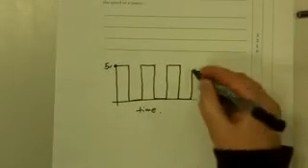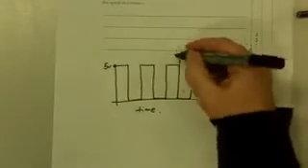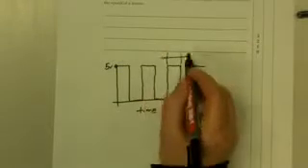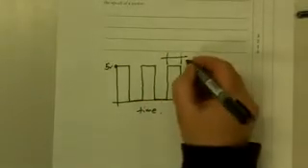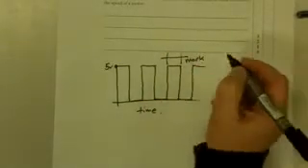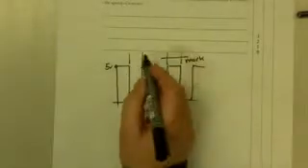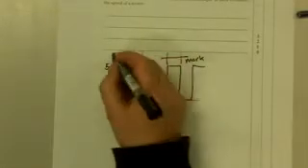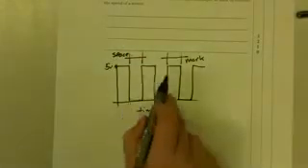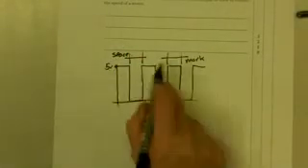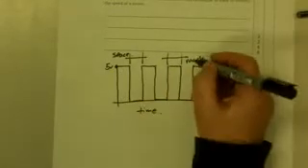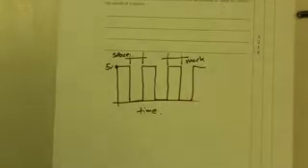And you need to label that pulse. That is the mark, and that amount of time is the space. Space is when there's no voltage, and the mark is when there's VCC, voltage output, 5 volts. The ratio between these two can control the speed. So what are we going to put?